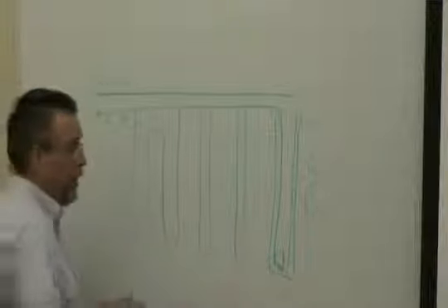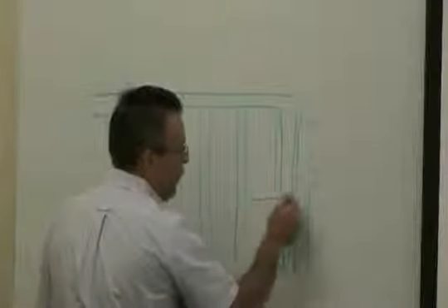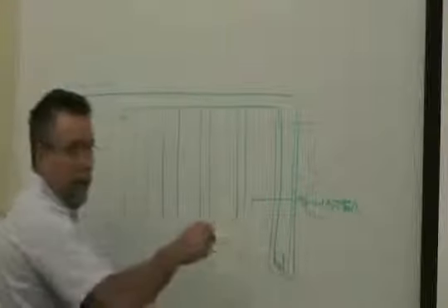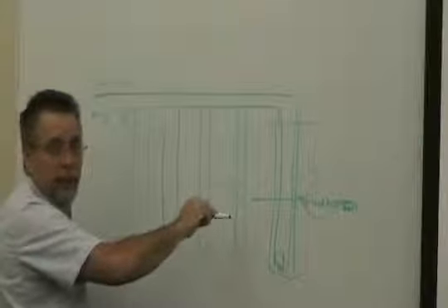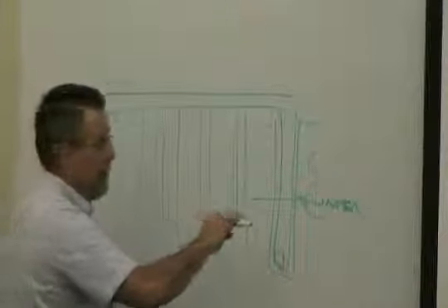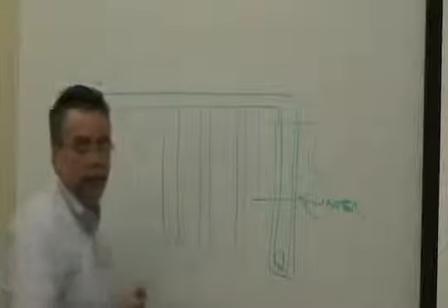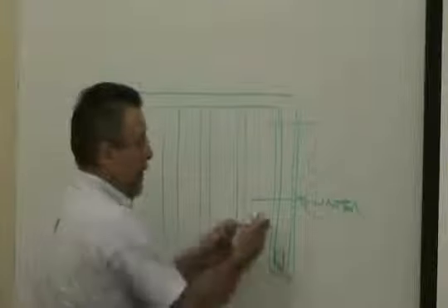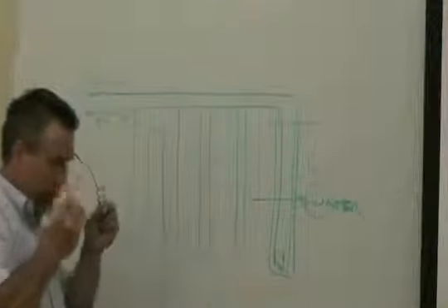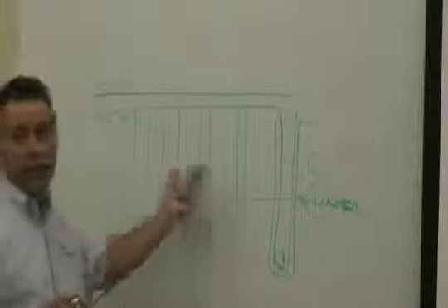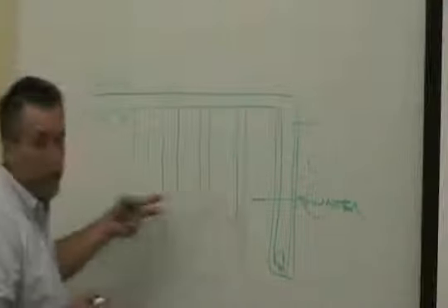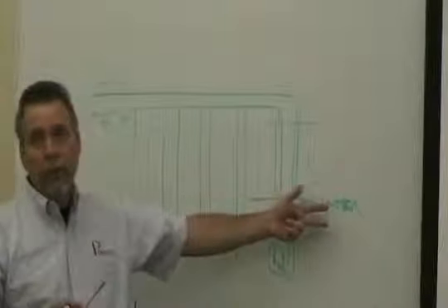The ideal ground is rocky with water flow through it. If it's rock ground with water flowing through it, you have an incredibly good heat exchanger. If there's no water flow through the ground and it's purely sand or dirt, then there's really no heat exchange. You're just heating the ground up, and eventually your loop goes bad. So ideally, you get high conductivity when you have water flowing through the ground.